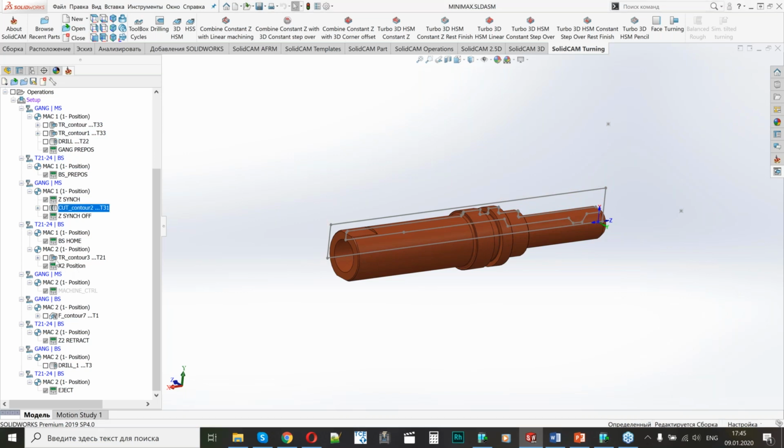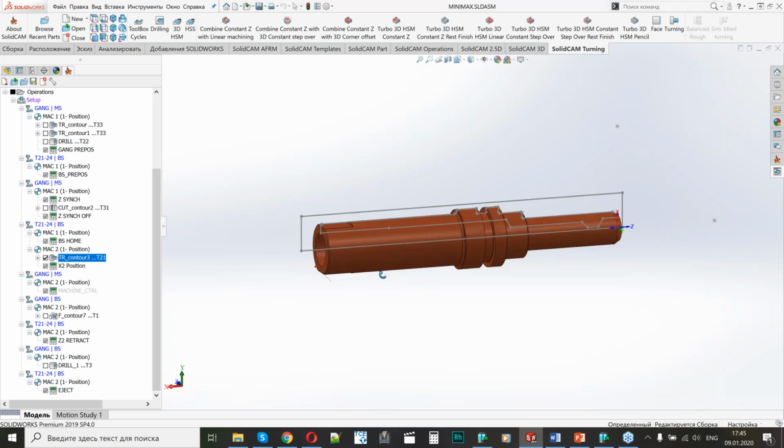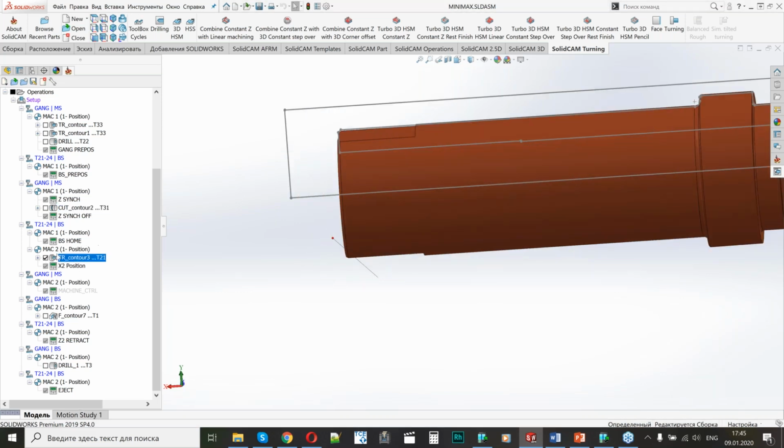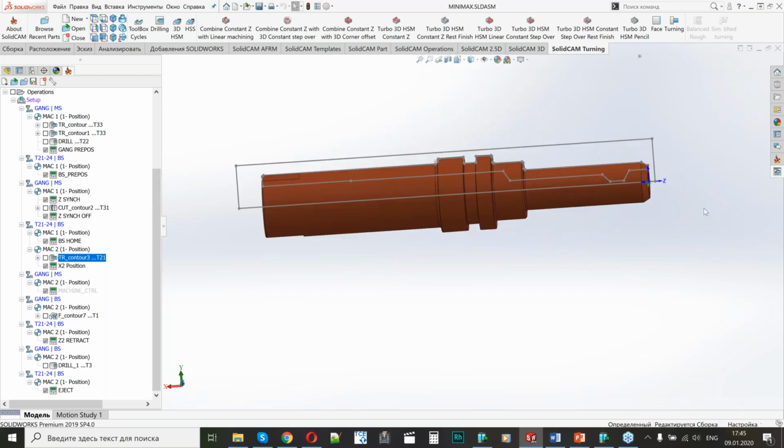I'll make the cutoff, transfer. Then I'm going to have the turning operation on the submachine, and then after the movement of the stock to its position right opposite the tool, back tool post, I can use milling and turning operations here. I'll just show very quickly